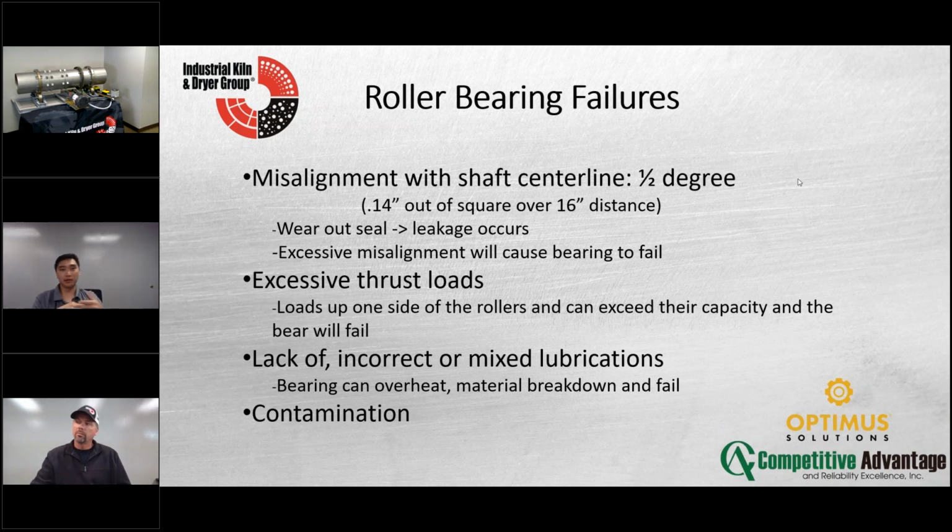It's cheaper to replace lubricant than to replace a bearing. Right. Okay. So when you do that, we do have different lubrications out there for kilns, and we will send you some of that information on what types. We do have different partnerships that we can get particular styles for you. But ultimate answer is it depends. It depends on the weight, the heat, the application. You've got to look at the system setup. Hey, but I appreciate it, buddy.